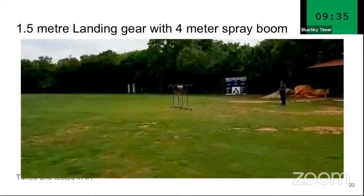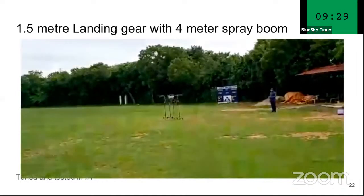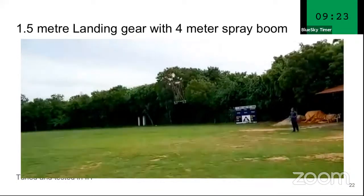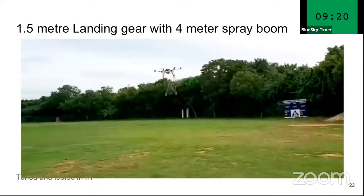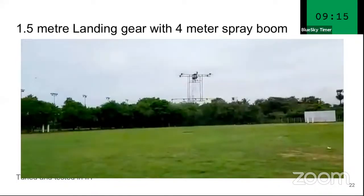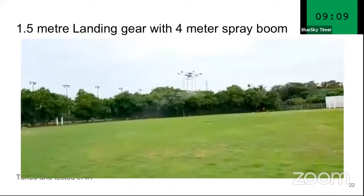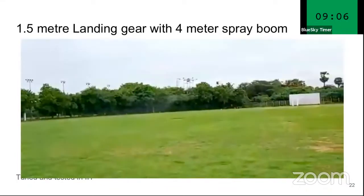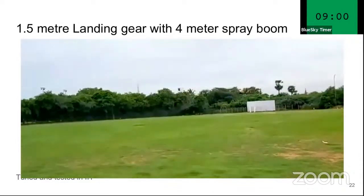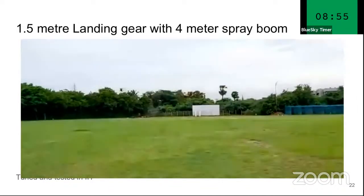So here is a picture of a long landing gear, a 1.5 meter landing gear with a 4 meter boom. This picture is taken in our cricket stadium in our campus as a demonstration. Another thing that this will show is that you want to align your rastering direction with the wind, so that you can actually have a wake along the spray rather than a side drift, depending upon the wind direction versus the rastering direction.